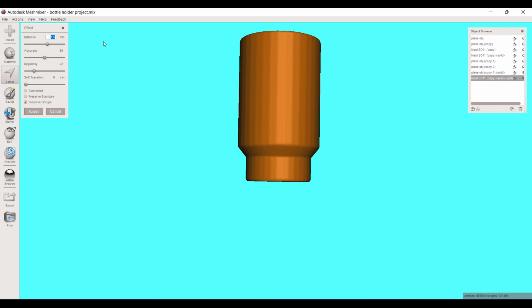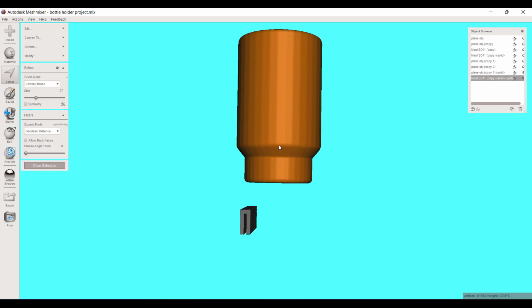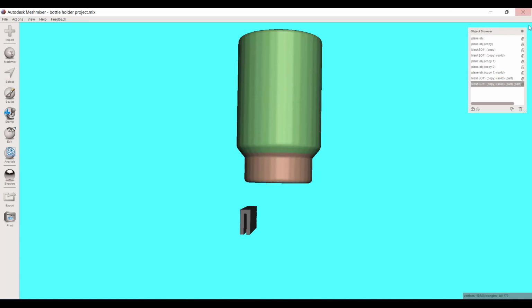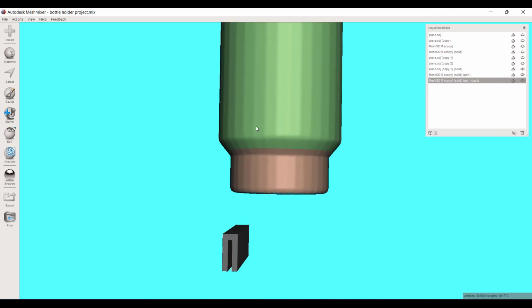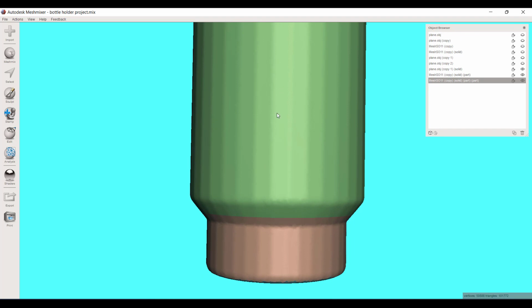All right, again, it defaulted back to 1.5. Let's this time make it 3. Click somewhere and let it refigure. All right, there's 3 millimeters. I'm going to accept it. Now, once again, while this is still selected orange, I want to separate that off because I want to show you something that will probably cause you some issues if you're not aware of it. Prior to separating this, I had the inner shape, and now I've got an outer shape to give this all a 3 millimeter wall thickness.